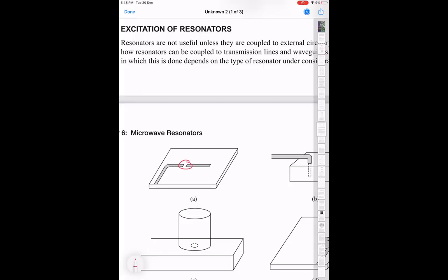So it's a CPW line, but again in this three-dimensional coax type of version, and this is a transmission line resonator with periodic boundary conditions. Unlike the ones we looked at so far, which had a short at one end and an open at the other end, this is just a transmission line wrapped around itself. But that is perfectly fine.